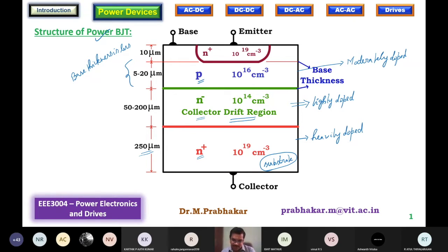The reasons we will discuss. That forms the base layer, and then we will have a very thin emitter layer, which is again heavily doped. Emitter is heavily doped because that is where the charge carriers need to be emitted from, or where conduction starts. Okay, so the structure that is shown over here is for an NPN transistor. This is even more popular, because the charge carriers are going to be easily mobile in an NPN transistor.